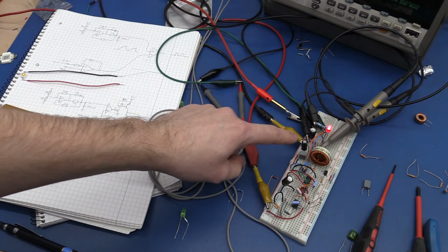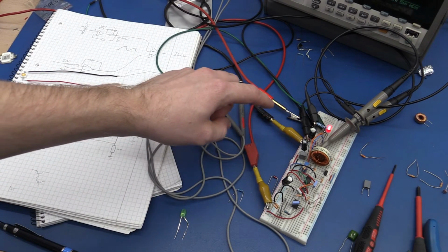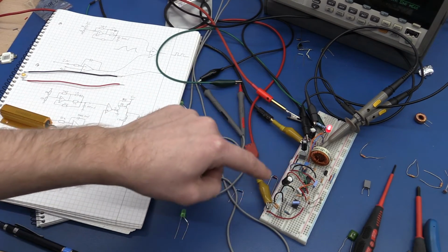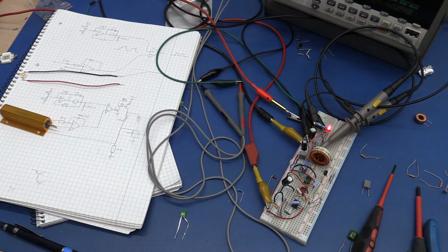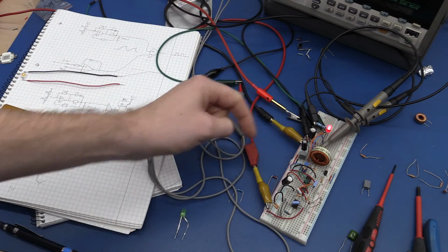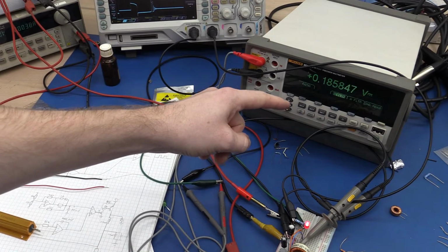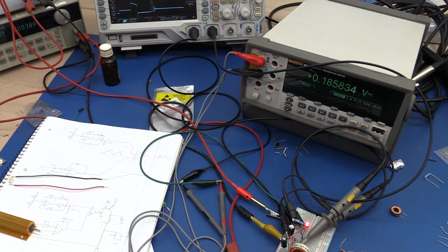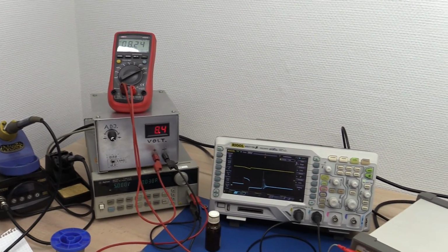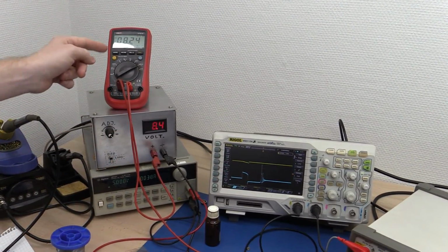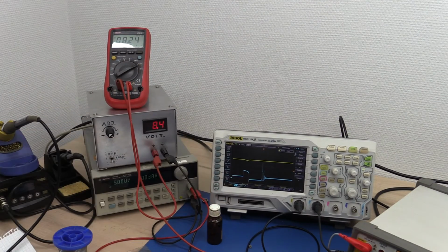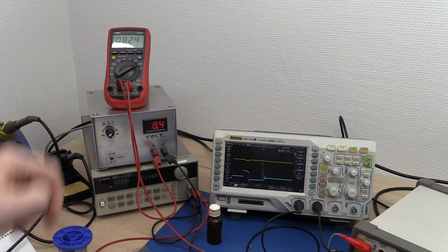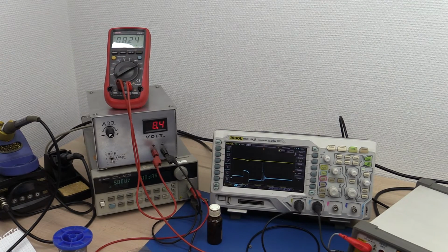So I have added the LED here, and I also added a separate power supply for the VCC. So now only the control circuit is powered from 5 volts. That way I can also see how much current we actually use from VCC. This meter here is measuring the LED current. I'm measuring the voltage drop across the resistor. Currently 18.5 milliamps. And over here we have the input voltage and current. So we're feeding our power supply with 8.4 volts, and you can see the current is 8.25 milliamps.